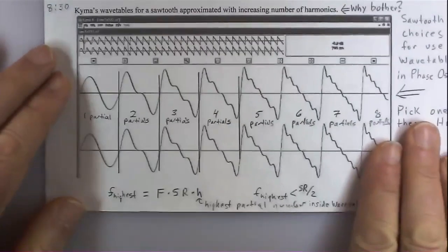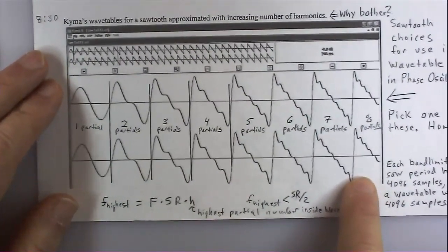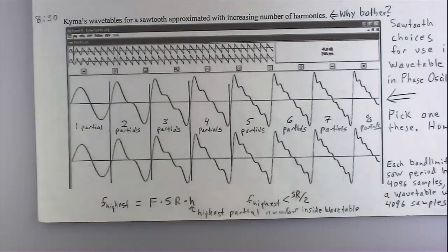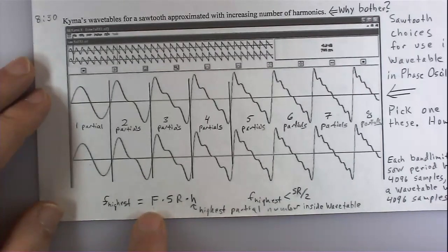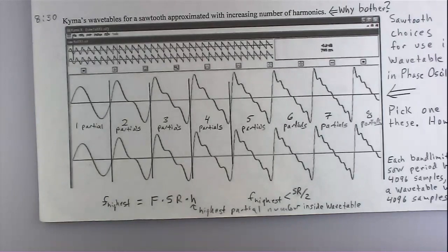You don't want that. When you are going to play a sawtooth, you've got to play a sawtooth where you have some number of harmonics in it. And that number should be, like it says here, the highest harmonic, the highest frequency you have. Oh, I should explain what these numbers are first. I'll get back to this. So what I should say instead is you want harmonics up to the half sample rate. You want all the partials in the sound that go up to the half sample rate, but nothing beyond. And that's a good sawtooth. And that's a real pain to make. A sawtooth is really quite easy to make in analog, but in digital it's a pain because you want to, again, include all the partials, all the sine wave components up to the half sample rate, but nothing beyond. So you can't have any sharp corners.